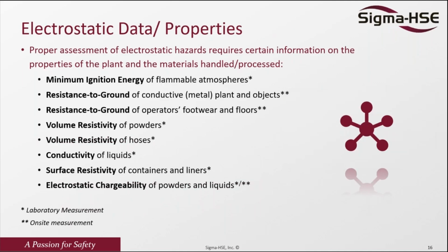So there are key parameters. In case you tell me, okay, Dr. Ade, come to my facility and do an electrostatic hazard assessment on my operation, I need to know some key parameters. That's where I'll come with maybe my megohmmeter, my field meter, which is JCI 140. So I'll come with all my various equipment to your facility.